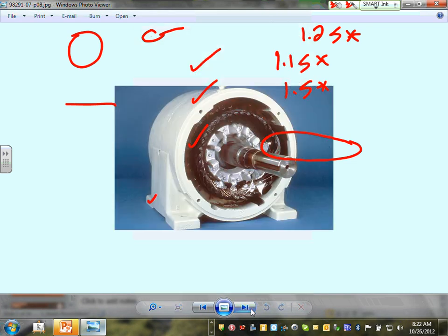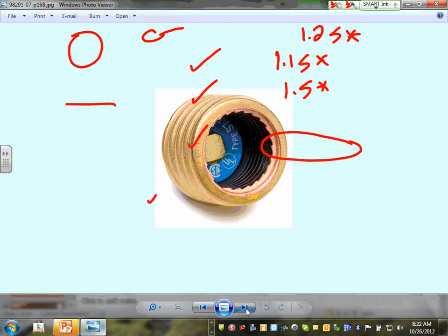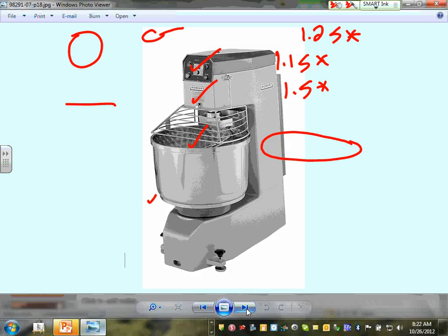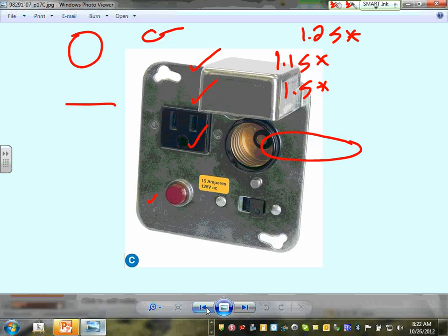These are a couple of pictures, guys, about the motor. Look at these charted motors because of applications. I'm going to move through them. Yeah, this is my favorite. Sometimes what they do, guys, for supplemental protection for motors, they add a fuse to protect the plugged-in motor for extra protection. So if you have a machine on a manufacturing floor or in a factory, you plug it in. You don't want to depend on the circuit breaker to protect it because it's expensive. What they do is they have a little box like this where you plug it in here, but there's also a fuse specifically sized to protect this machine that's plugged in here.